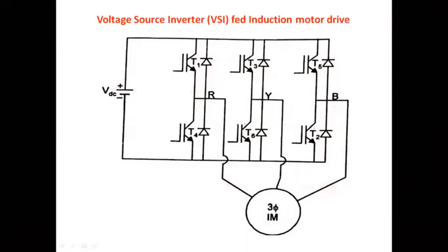So if you want to regulate the voltage and current quantities, you need external means. External voltage control and external current control are required for a stepped wave inverter. Whereas the PWM inverter has the function to control both voltage and frequency internally in the converter. There is no external converter required.